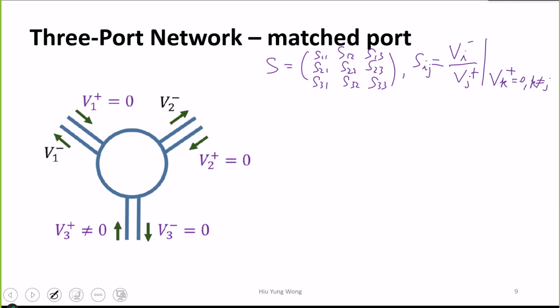You don't know what I'm talking about. But let's look at the ports again. This is a microwave. And the way we analyze microwave is look at an incoming and outgoing signal, right? Do not think of a regular circuit that you use to light up your bulb, that you only have positive and negative 2 ports, and you always think about current going in one direction. Voltage is just there. It is a microwave, it's a traveling wave. So we can analyze it as a wave going in and a wave reflecting. And of course, the total voltage is the superposition of these two voltages, right?